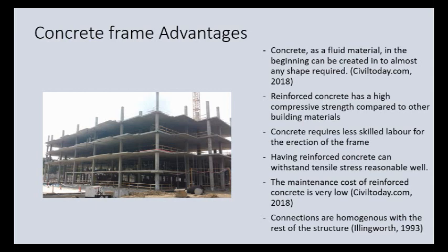Concrete as a fluid material in the beginning can be created into almost any shape required, providing very little limitations on design. Reinforced concrete has a high compressive strength compared to other building materials. In other words, concrete offers a good resistance to being pushed together, whereas tensile stress is being pulled apart. Concrete requires less skilled labour for the erection of the frame, and reinforced concrete can withstand tensile stress reasonably well, again being pulled apart.